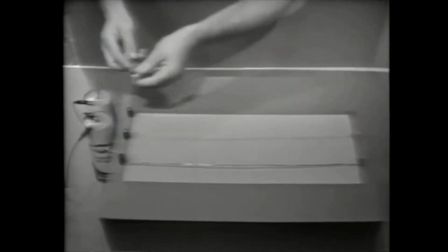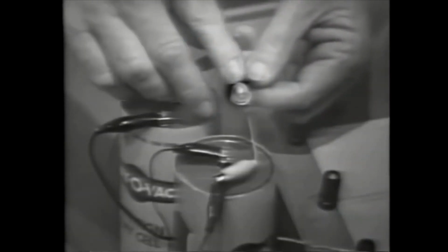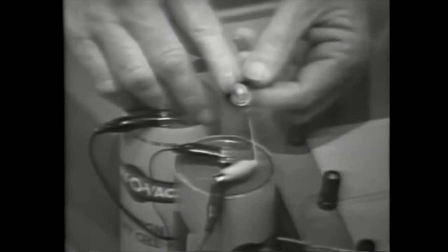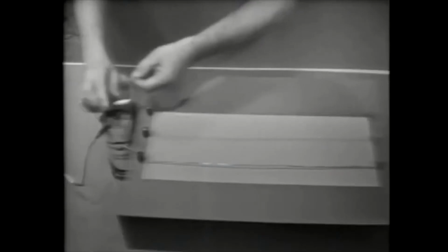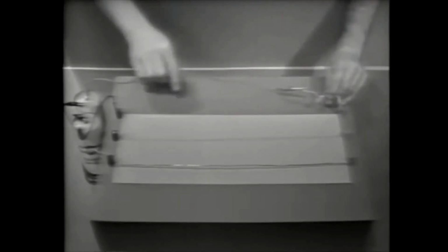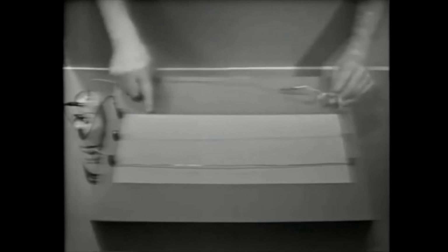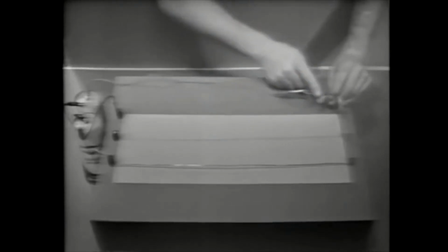Before we begin, let's check the intensity of the bulb with just the resistance of the bulb opposing the current from the battery. As you can see, the bulb is lit very much, very bright. Now, in the first example, we'll use the small wire, and we'll see the factor length and how it affects resistance. Now, with the connection here and here, the battery must force current through the resistance of the bulb plus the resistance of this wire. There's very little current through the bulb.